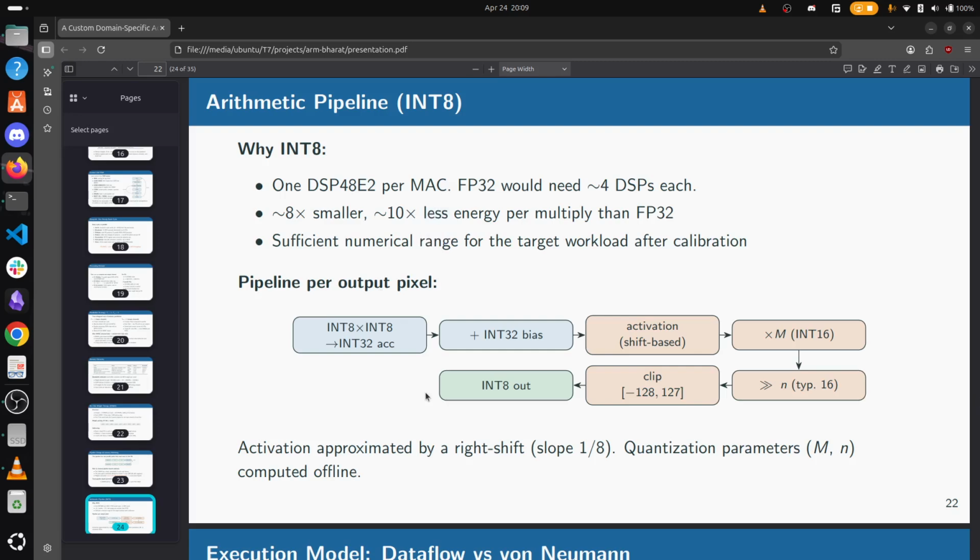So the benefit of the accelerator is that we can design our accelerator to be extremely fast with int8. So we can completely ignore other data types like floating point and a lot of the other data types such as dword, and there are multiple data types in a modern CPU. So this is again the same trade-off between generality and speed. A CPU has to support multiple data types, so it will take much more logic and much more transistors and much more area and much more power because it needs to support all the possible data types. Whereas our accelerator can be highly specialized and it can only target one data type, which can make it extremely power efficient and extremely performant.